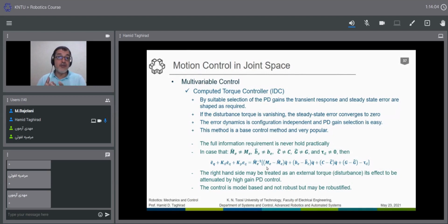This is true if we know the parameters of the system. If we are not accurate, we are not fully linearizing, but we are reducing these terms by 90%, depending on how well we know. If we know them 99% well, only 1% of the nonlinear term will remain. This means that to use such a thing, we need to do very accurate modeling and also very good identification. If we don't have the identification or the calibration in robotics, this is not good. However well we do, still something will remain.